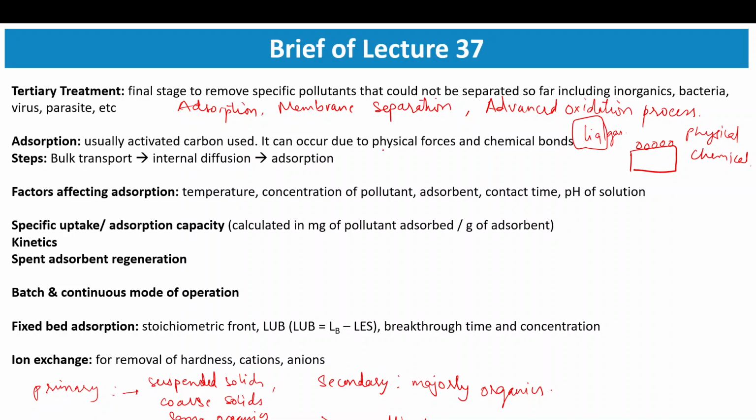Say, for example, if you have wastewater, it can have pollutants in the form of, let's say, some amount of organics left, heavy metals, and some pathogens. For these different types of pollutants, adsorption will try to attract them, and obviously not water, and they will adhere on the surface.